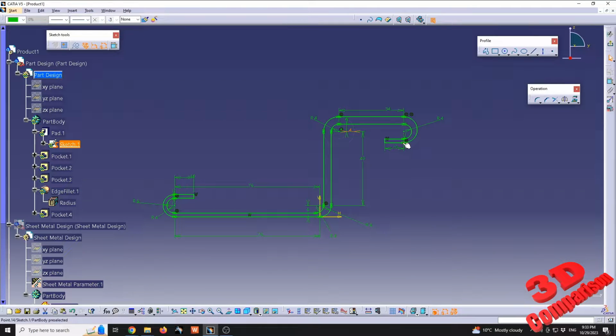We have it on the top. Over here, there's also an offset. I'm going to increase that to 4 millimeters as well. We're going to have another one over there underneath that constraint, so 4 millimeters. And we see that if I added this 4 over here, this sketch will no longer be properly defined. So I'm just going to delete this 6 value over there.